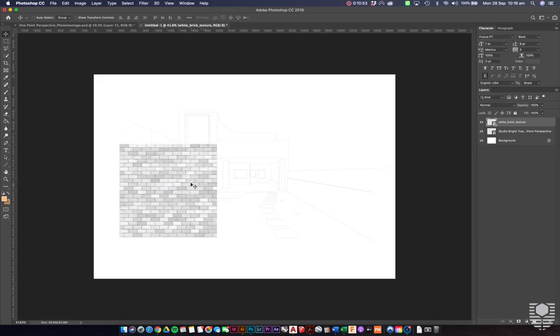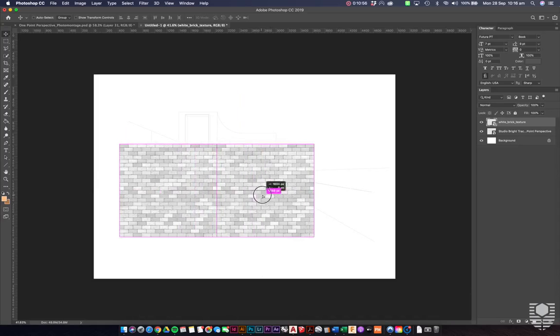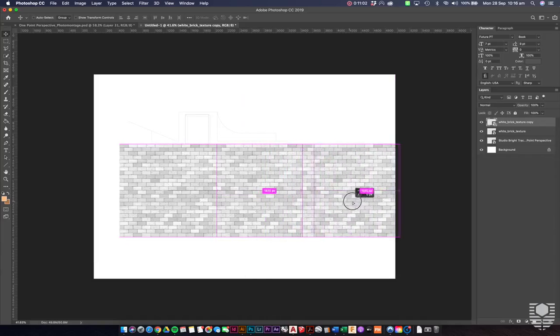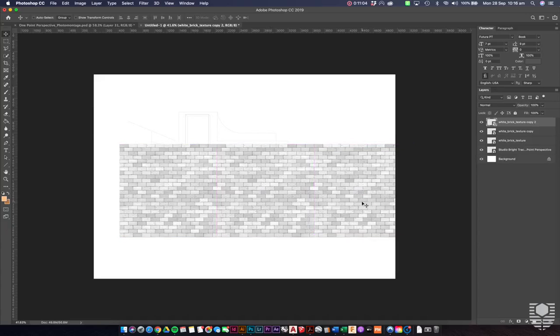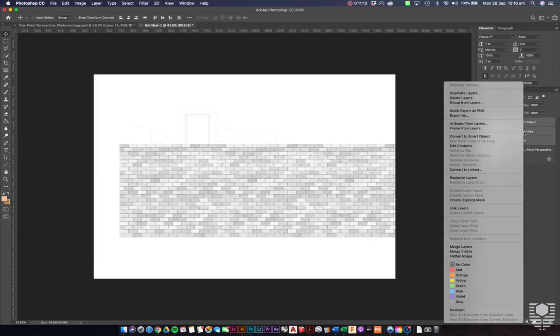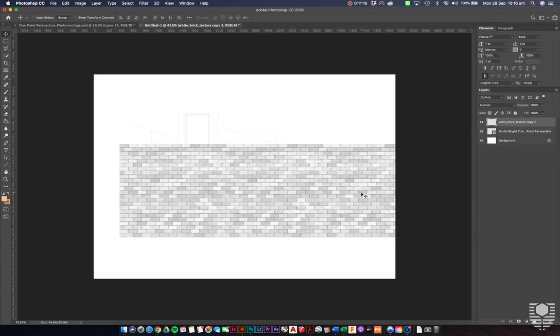So what we can do, when we have what's called a tiled texture, which most of them these days are on textures.com, or if you're Googling white brick texture, you've got that, we can just copy by holding down Alt and dragging across your shape, and it will create a seamless texture like this one here. So now I should be able to merge these together and then use that same technique. So let's grab all of those ones over in our Layers tab, right click, merge layers.